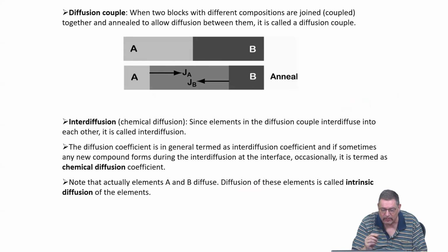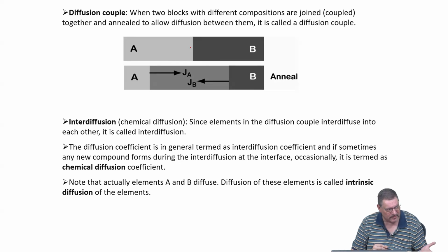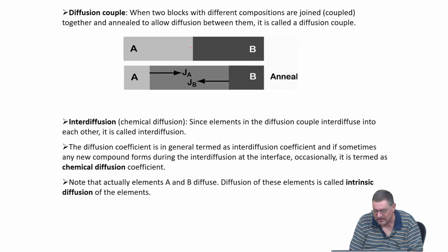So you bring together two dissimilar materials this time, and across the original interface, diffusion fluxes occur of some constituents from the A side to the B side and some constituents from the B to the A side. Vacancies are now included in the picture because I'm talking here about substitutional diffusion, even though for interstitial diffusion the picture would be the same.